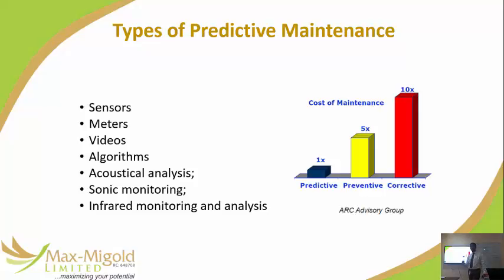You know, there are some pumps like fire hydrant pumps. You don't want to go opening it up because you want to service it. Every now and then, just check, take the setting. It has this little dial there. Note the pressure, note this, note that. That's all you need. As you keep recording it, you are knowing the state of that equipment. If it goes into a certain range that is red, this thing needs to be dealt with. Even if it's not yet red, and you've seen the way it dropped from a certain level, it's tending towards going into the red range, then you want to do something about it.